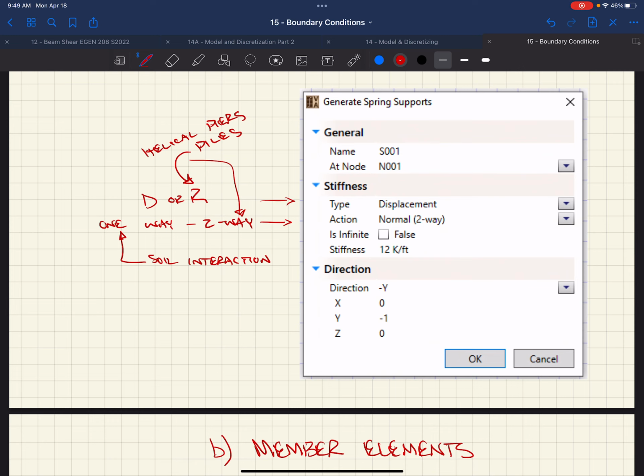You're talking helicals with void forms, so that it's legitimately just sitting on them. Usually that's how you would design them. But it depends. I've done them where there wasn't any void forms either. And then you get a little bit of bonus, the soil's there, right? But then stiffness attracts load, so you don't really want your structure to move more than half an inch. So if you move your building half an inch, how much is that soil that you cast on top of really going to get?